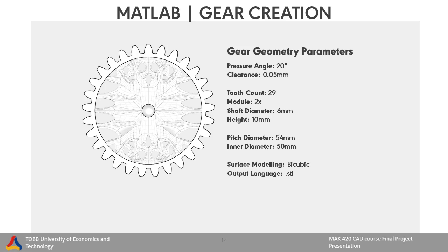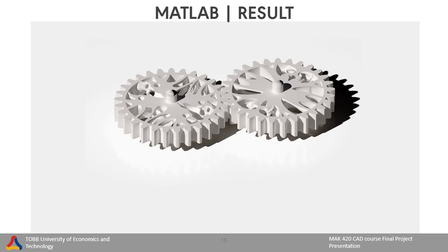To smooth the geometry while allowing necessary controllability across it, bicubic Bezier surfaces have been selected as the surface modeling approach. And the final geometry has been reached with a decrease of 70% in mass, while having 150 more surface area